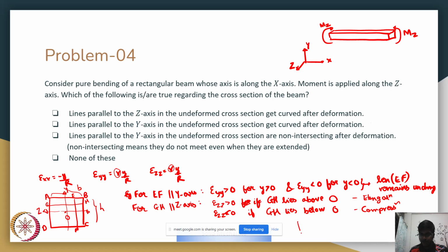But if we do a simple analysis, it would seem like these are the lines that are occurring. But if the shape ends up becoming like a trapezoid, then you can see that this angle is not equal to pi by 2, which should tell you that some shear strain and shear stress are generated.